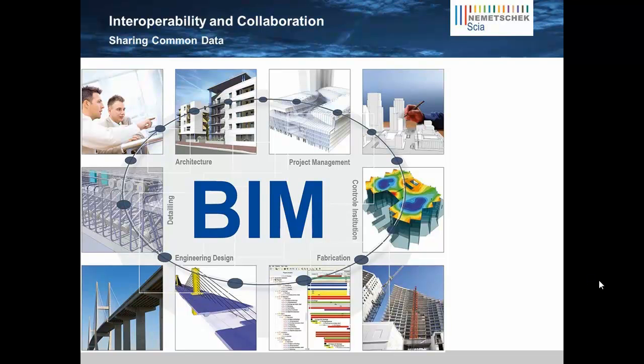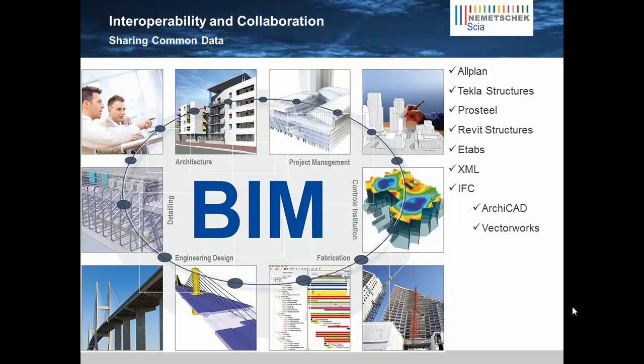To that end, if a program has an open API like Allplan, Revit Structures, Tekla Structures, Pro Steel, or ETABS, we can write to that. We can also link to programs via XML. For BIM and plant design, we have certified support for IFC, which gives us a vendor-neutral way to exchange models with any BIM-compliant software program. And we support common exchange standards like DXF, DWG, VRML, PDF, just to name a few.